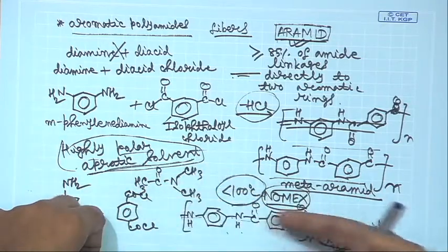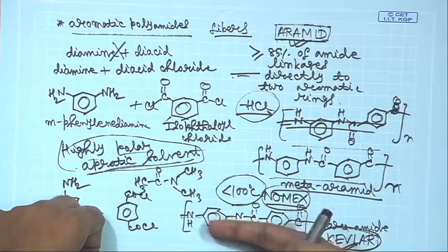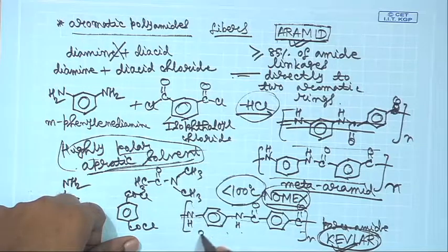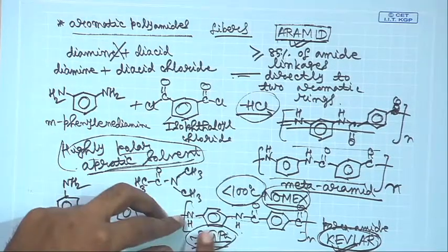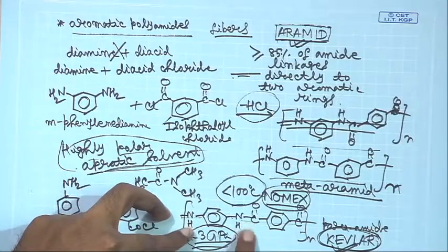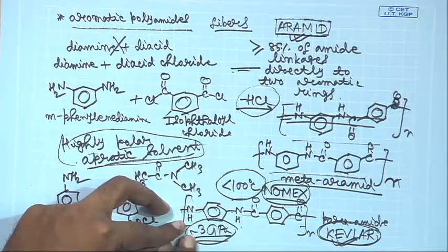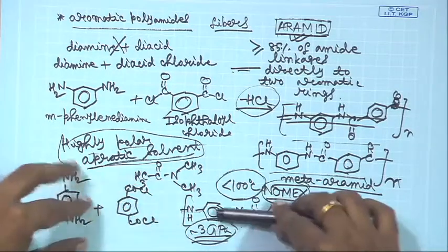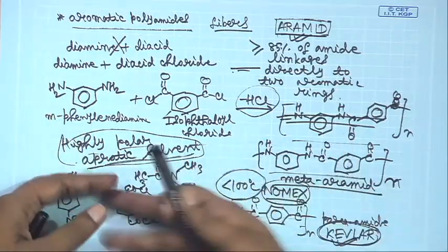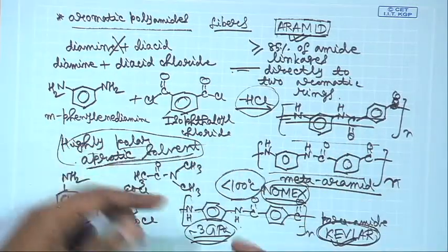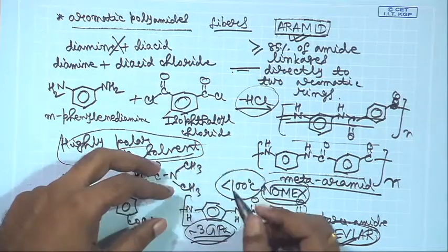All these molecules will orient along the long axis of the fiber, and that will give the fibers enormous tensile strength, up to approximately 3 gigapascal. And you will have all these hydrogen bonding interactions in the transverse direction. In the longitudinal direction they will just pack nicely, parallel like that, and also you will have these pi stacking interactions between the aromatic units of the subsequent layers.